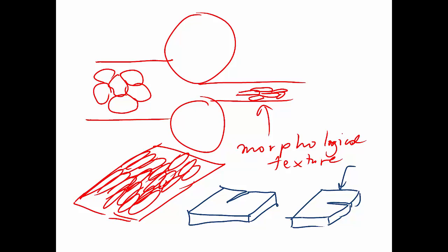And there are some empirical arguments that can be used for this. So for example, people say that the defects scale with the grain size, and in this case the grain size is not isotropic, so defects in this direction here are going to be proportional to this size, while defects in these directions are going to be proportional to that size. And obviously this kind of defect will reduce the performance of the microstructure in that direction.